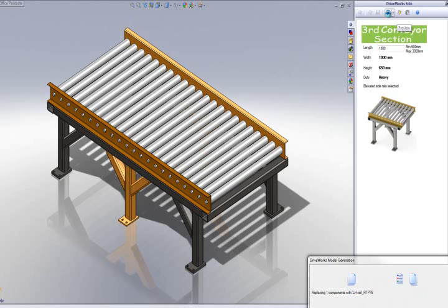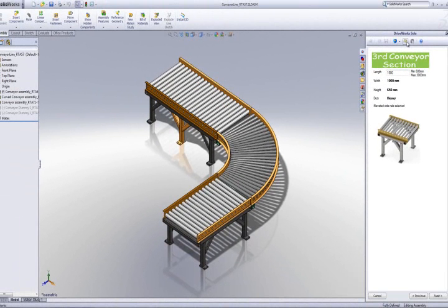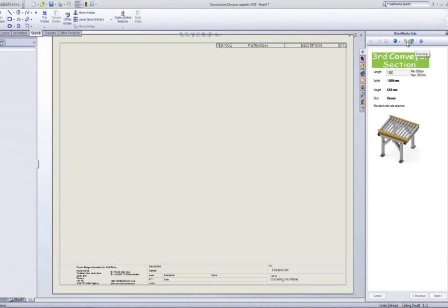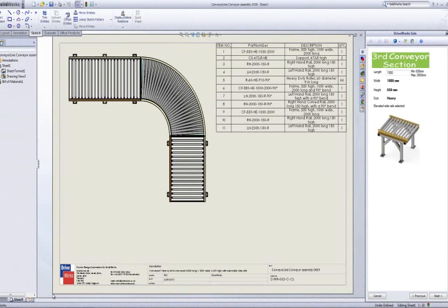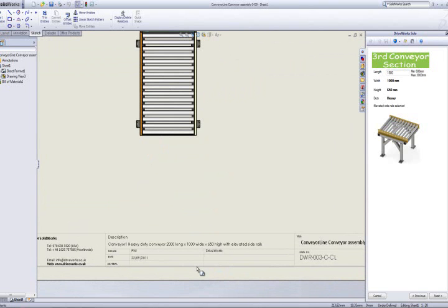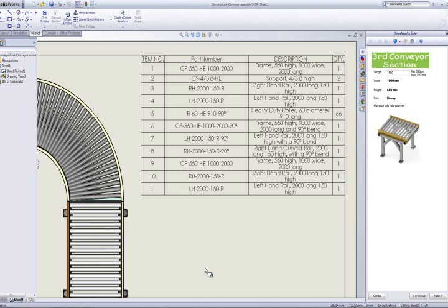Once the engineer is happy with the model, they can also preview the drawings that will be produced with this project. Again, like the model, drawings can be previewed by clicking this button here. This uses the temporary models just created and generates the drawings captured against the models, based on the rules created in the project. Notice that each drawing will open, and on each drawing sheet the drawing views will rescale, resize and reposition based on the rules created. Taking a look at the drawing, you can see that the information from the project has been populated into the borders. The bill of materials has also been updated, and so have other notes on the form.